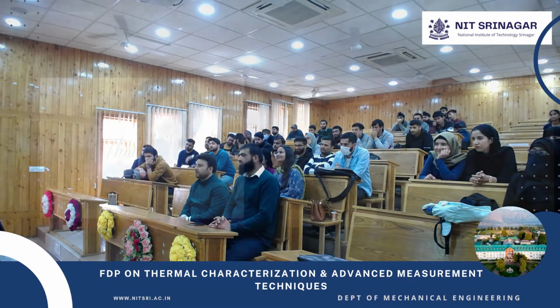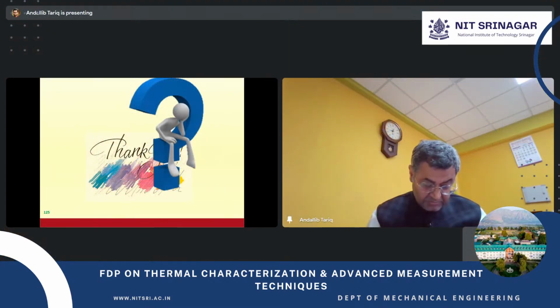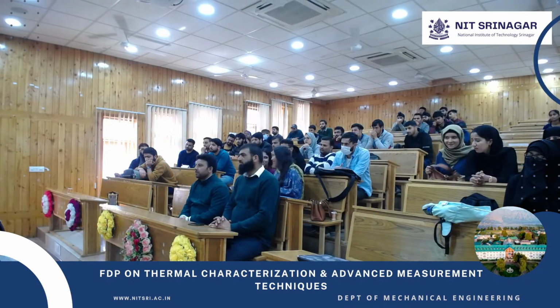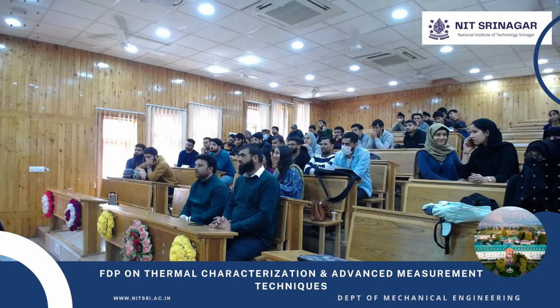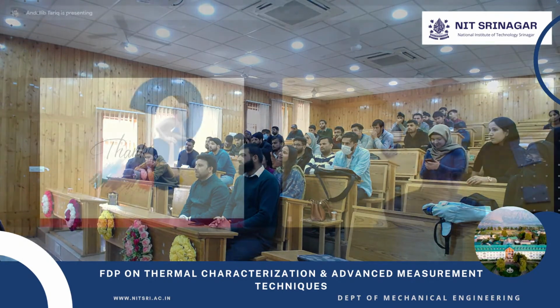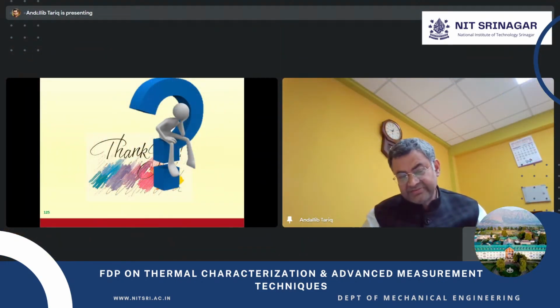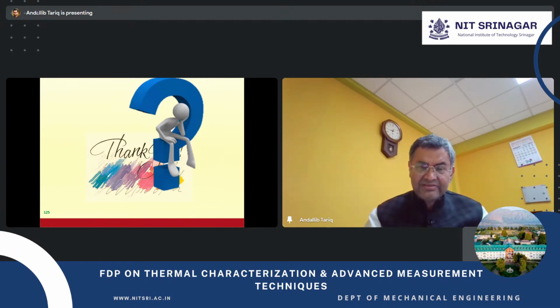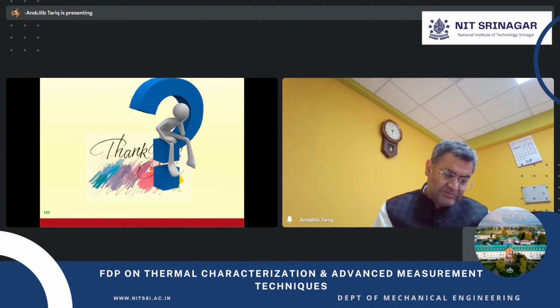Professor, earlier you were talking about liquid crystal thermography. Have you used liquid crystal paint or sheets? Sheets. Okay, fine. You could have used paints of the grades of liquid crystal paints. Yes, that can also be done. The temperature range of these liquid crystals is not so wide, on the order of 15. Okay, that's fine.